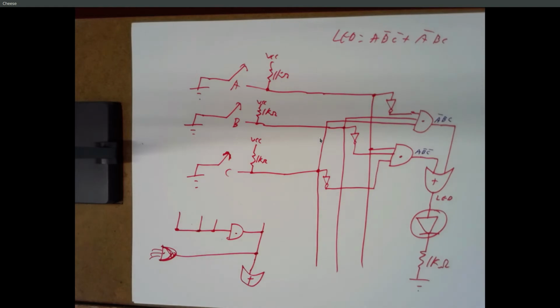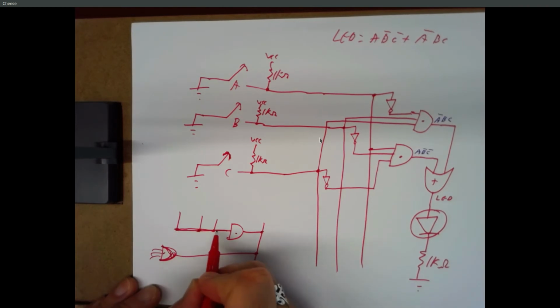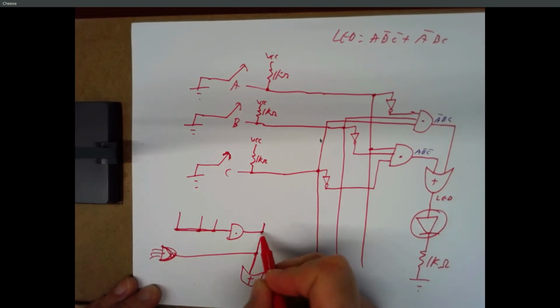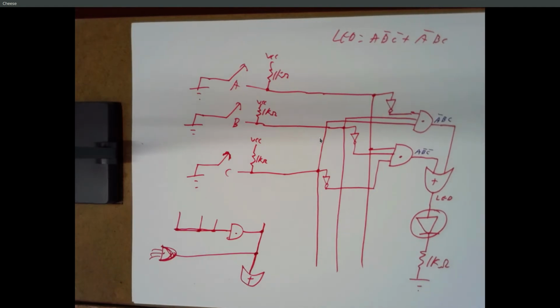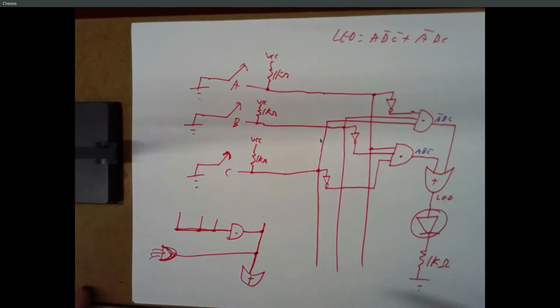That's a shorthand we use when we draw fuse maps because we're not building that part of the circuit. The fuse map part of the circuit is fixed. It's always exactly the same. All we're doing is showing where we want to connect things together by drawing little X's at the crossover points. So we use an abbreviated view of the circuit, which is using these tricks. Draw all of these on one line and draw all of these on one line. But it's not a valid circuit diagram, right? And if you tried to build this, you'd short out your components. So we don't ever draw that when we actually do wiring diagrams. It's just an abbreviation.